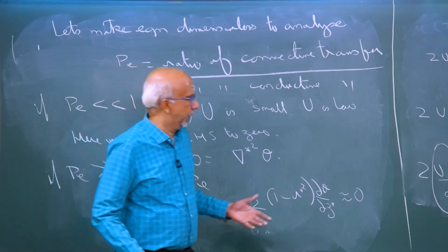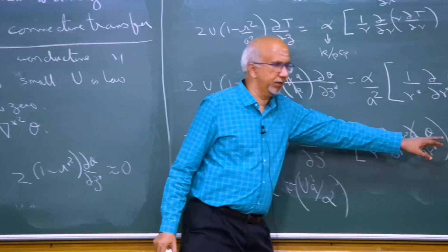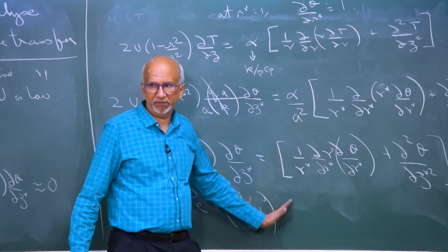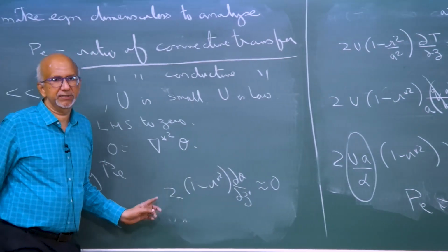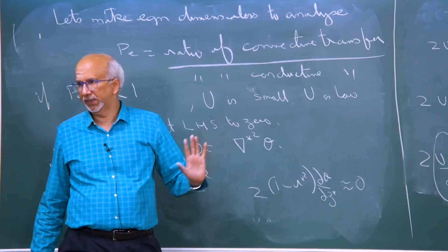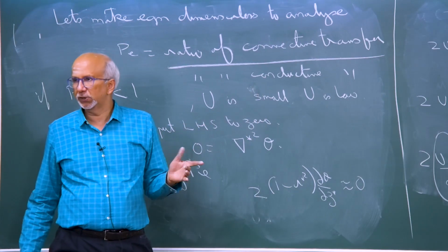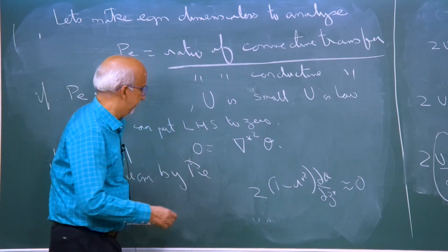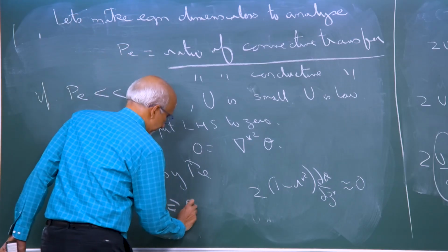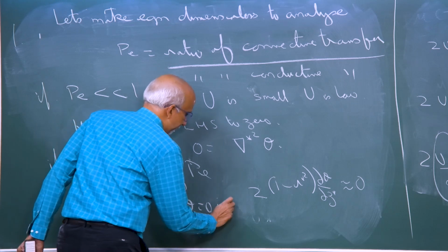We are assuming that all of these are going to be of order 1, so that is not going to go up to infinity. I am dividing by Peclet number which is large, so that becomes 0. So this means the temperature is not changing in the z direction. So in this limit, I have a problem in the sense this implies theta is 0 in the pipe.